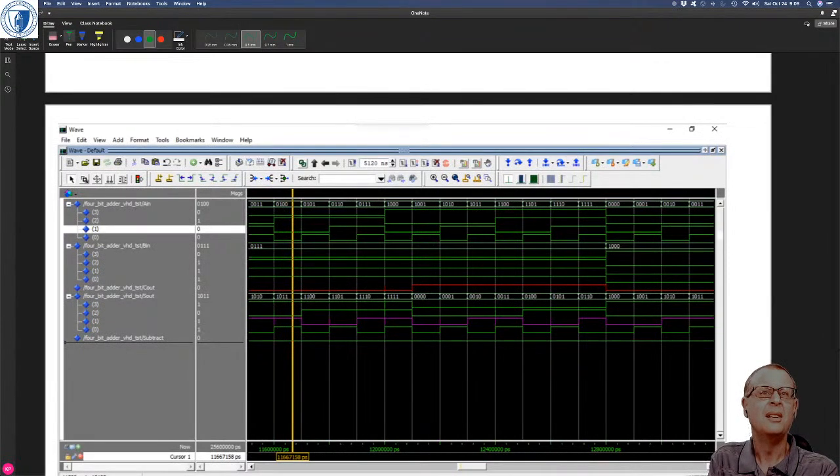These are a bit hard to see, but there's glitches here, there's glitches here, there's a lot of glitches there, right? And it's primarily because of delay paths through the logic, the way we set up the logic. And the problem is we are not using the power that we have with VHDL, right?